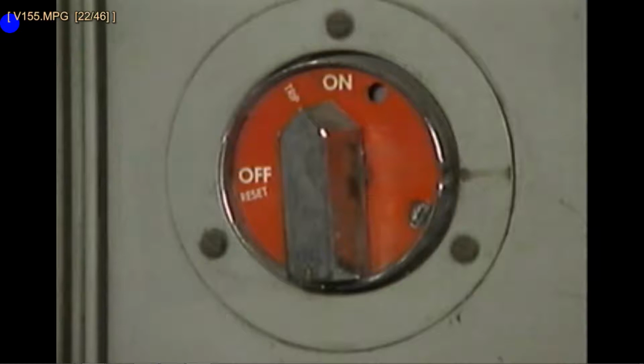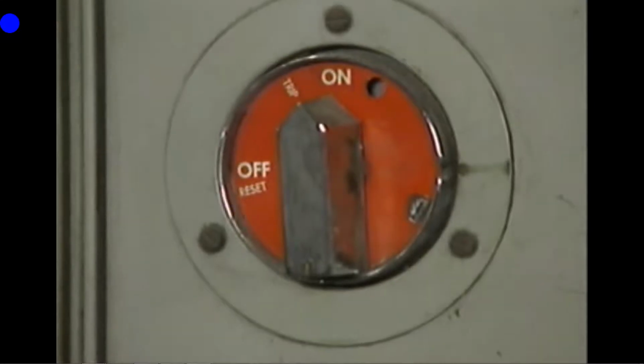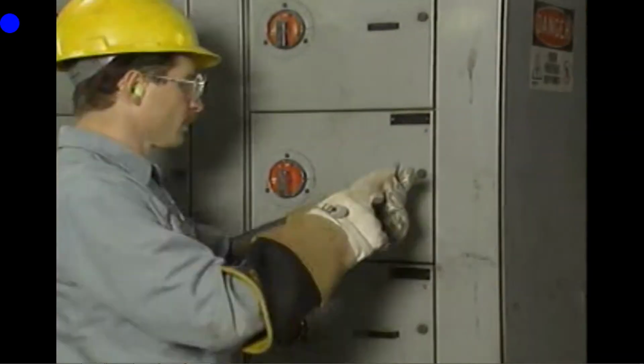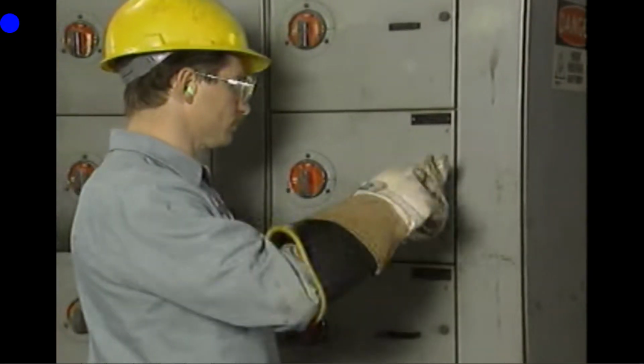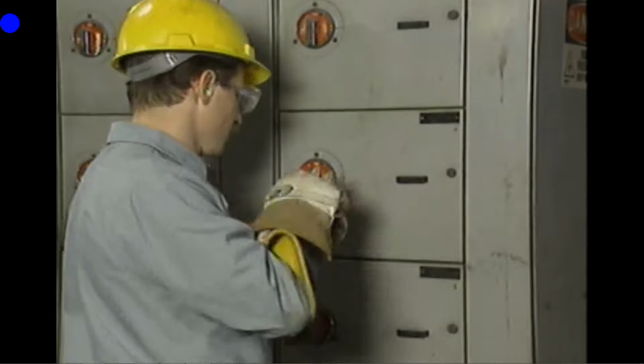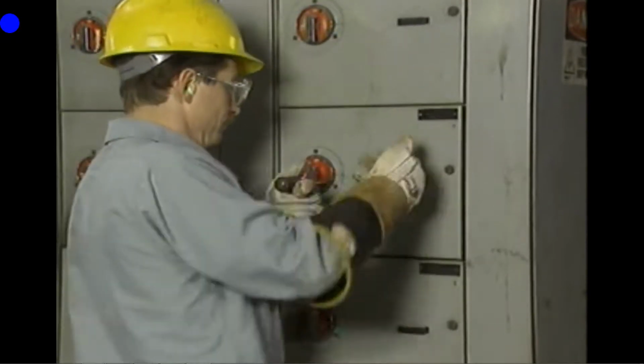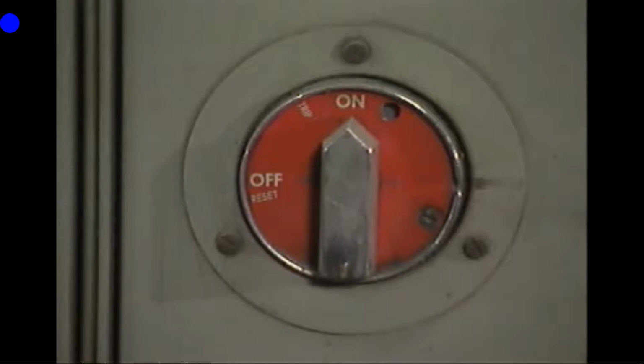In this part, we'll look at how you can troubleshoot an energized AC motor controller. Basically, there's one major reason for troubleshooting an AC motor controller while it is energized. Shutting down a controller can sometimes interfere with the operation of other equipment in the facility. For example, when 2 separate control systems receive their power through the same power supply breaker, opening the power supply breaker de-energizes both control systems, and that could be a problem.